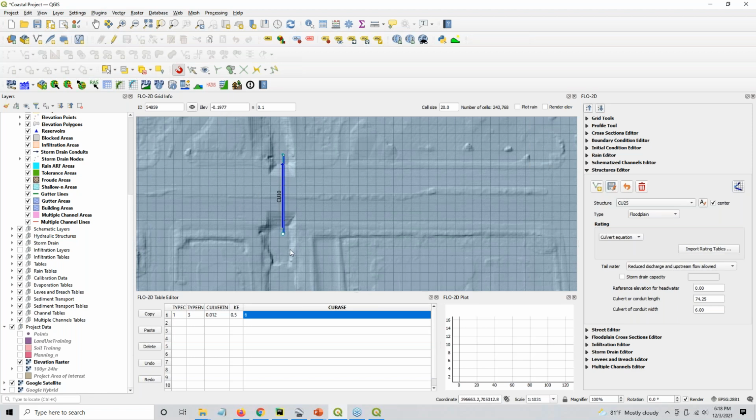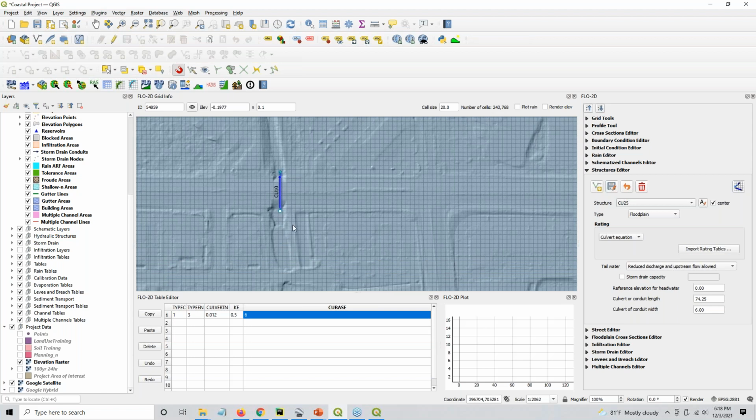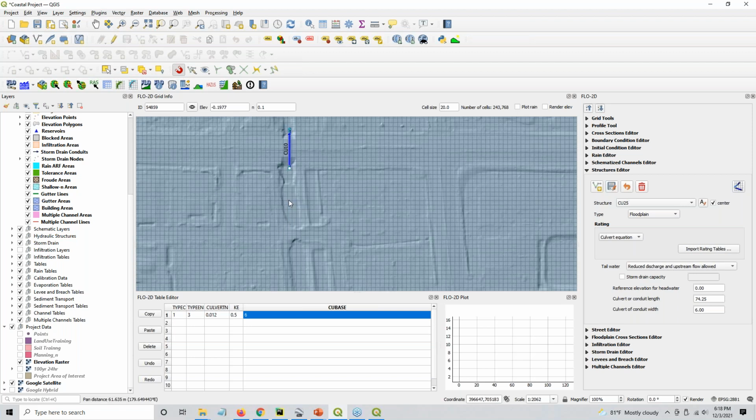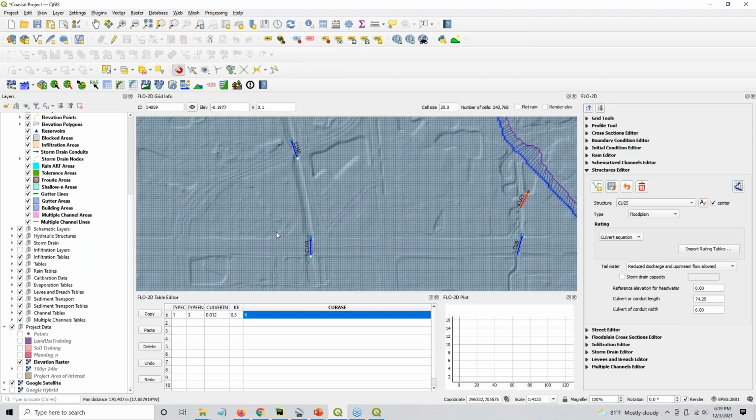negative 0.19. Now, unfortunately, that's a little misleading because this is a coastal model, so all these are full and we're not getting that bathymetry data. If you wanted to put real bathymetry data in here, you'd see that, or you could put this in as a trapezoidal channel, but you see that there's a bit of a drop structure or perhaps a gate right here. I also took a few of these structures out, so this one's missing completely. That's okay. I'm not really modeling every single channel in here, only the important ones that cause quite a bit of drainage.